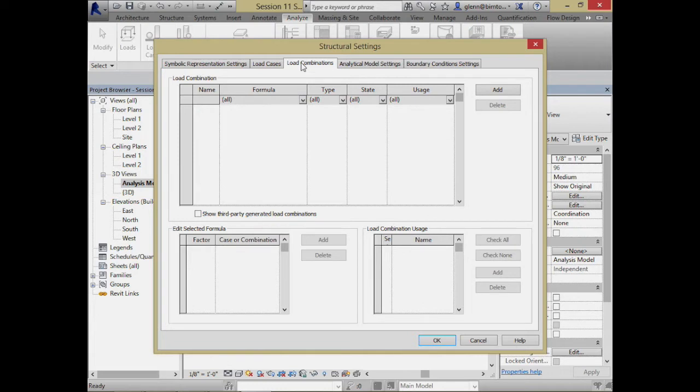Almost all of the structural analysis tools have their own load combinations built into them. So you can say, what is it? Is it 1.6 times the live load plus 1.2 times the dead load? Or the 8 other cases you're supposed to be considering also. So you can define all those different load cases. But the truth is, you don't tend to need to do it because the analysis tools will have those combinations built in there for you. But you can define your own load cases.